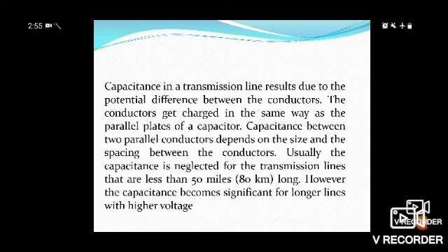Usually the capacitance is neglected for transmission lines that are less than 50 miles, that is 80 kilometers long. In miles we can say less than 50 miles. However, the capacitance becomes significant for longer lines with higher voltages. So for that we have to know about the capacitance of a transmission line also.